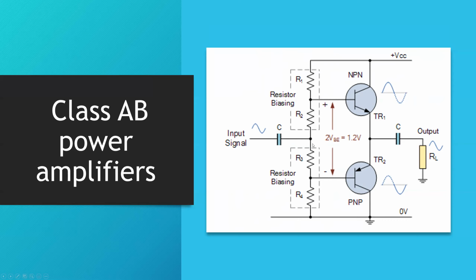And this is unwanted, since if the resistor value is changed due to an effect of temperature, the amount of current passing through these transistors would change. Thus, the output would change also. So this is an unwanted change, and this will cause the signal to slightly differ from the input signal.